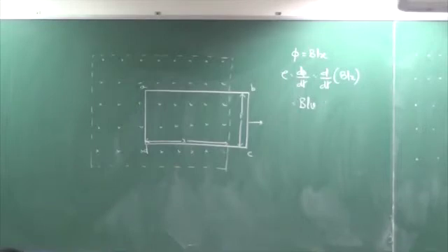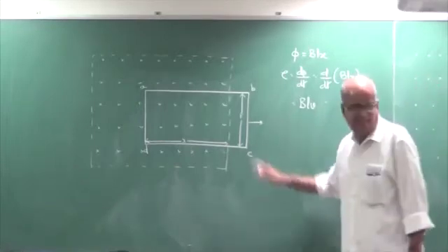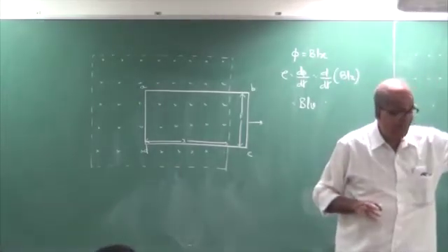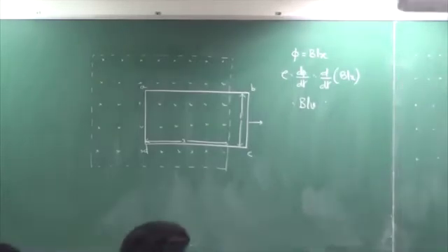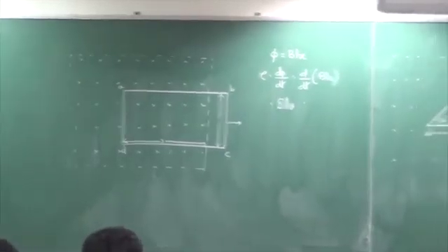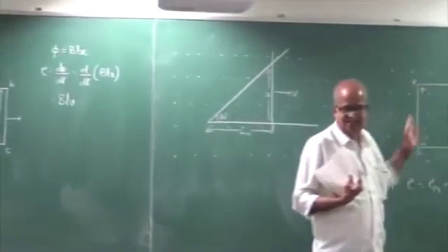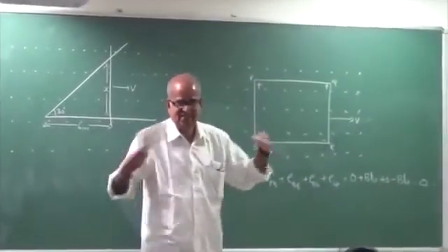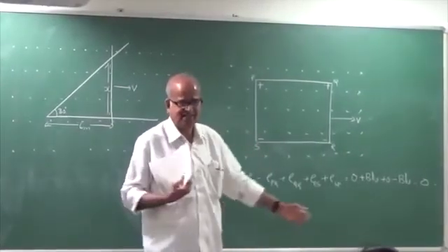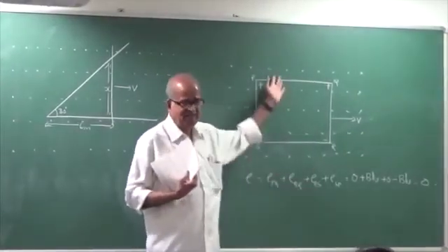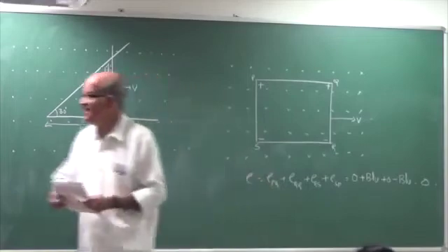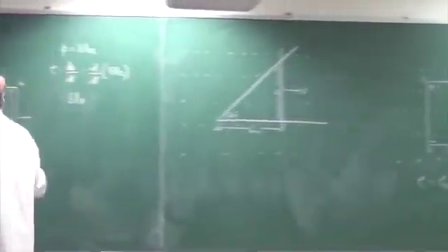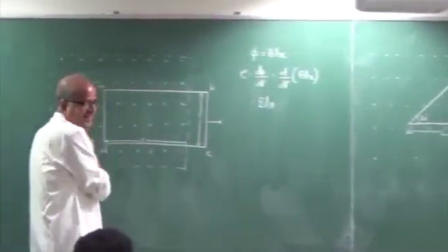You see, the interesting thing is, there we saw when the entire loop is within the field, the two EMFs are induced with a tendency to drive equal currents in the opposite direction. So, net EMF is zero there. There is no EMF in this, but there is an EMF that is induced in this portion, correct now?